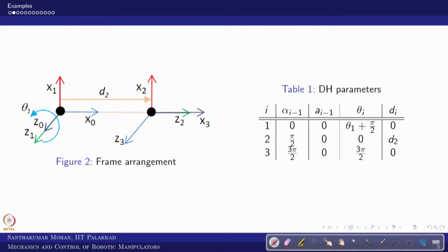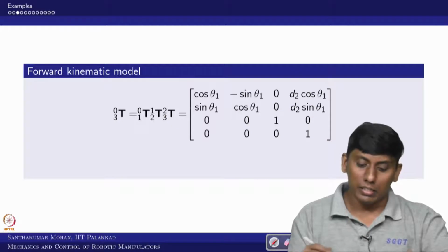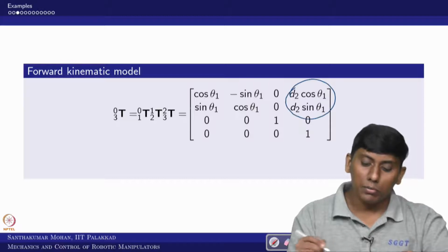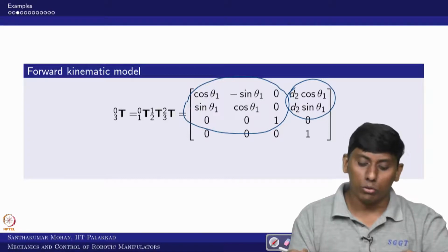So you can see which we have obtained. So now what you can see, whatever we have written, that all comes into the picture, right. So in the sense, this is the variable and this is the variable. We can substitute this into individual arm matrices, and then we can see the DH representation finally giving forward kinematics, right. So that we can substitute and finally multiply. You can see this is the final multiplied matrix that you get. So you can see that this is the position vector which we have written, and this is the orientation or the rotation matrix.